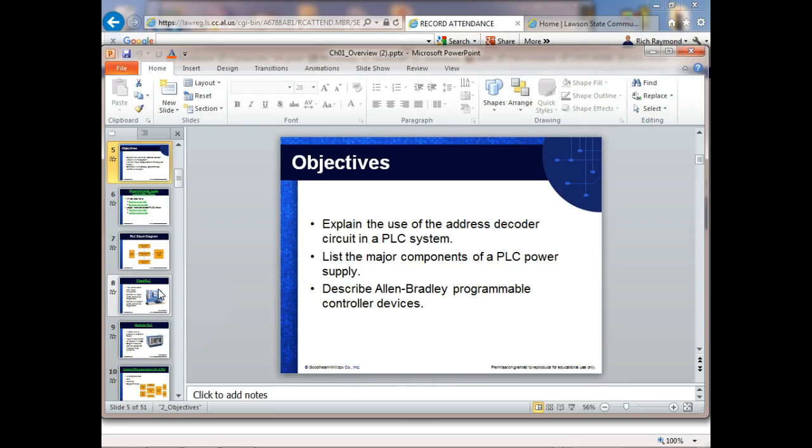We don't want doctors to go in and be able to change our automated nervous system, or it would probably kill us, right? We'd go blind or something like that. So this computer's probably got ROM in it, but usually the problem with ROM is it's really hard. The only way that we could upgrade, if something changes, would be to pull that chip out and put a new one in. And then that means the chip itself is going to have to be in a socket, and automatically you start adding more cost to the system, right?